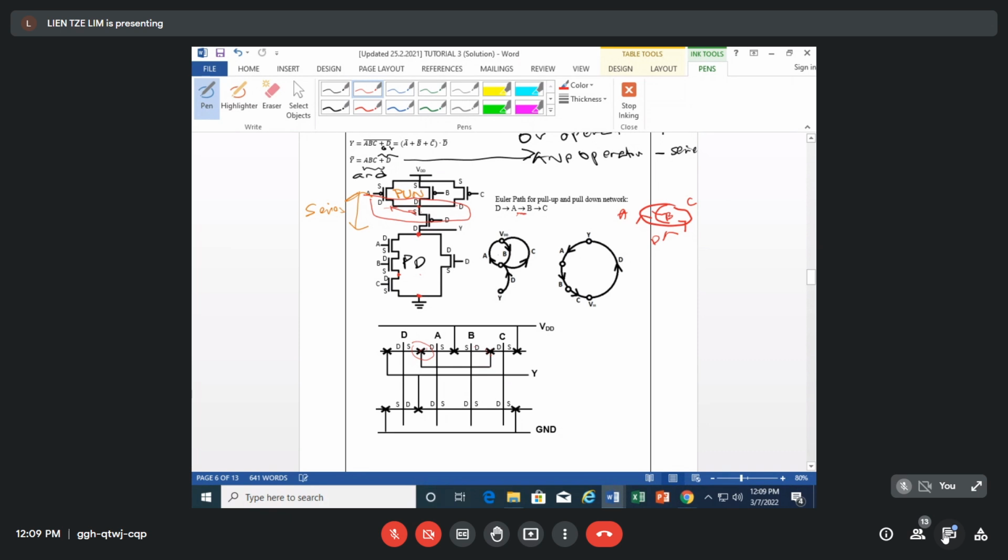If we didn't draw these contacts with these connections, your stick diagram is wrong. You need to make sure that you understand all the connections here and then draw them all in the stick diagram. If you miss any part, we consider your stick diagram incorrect.